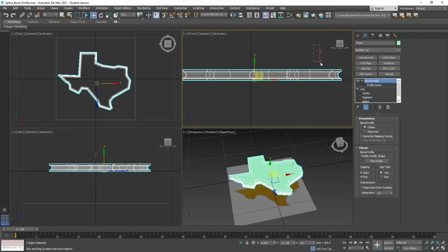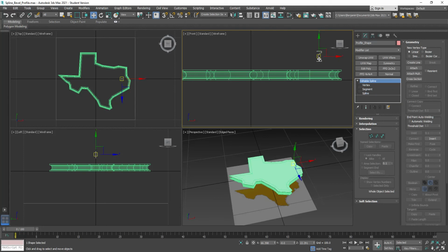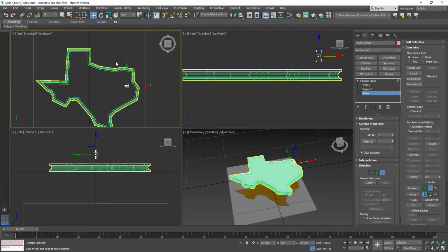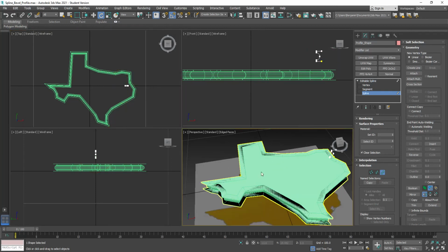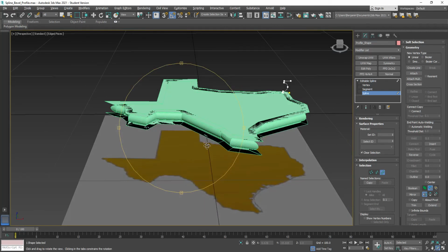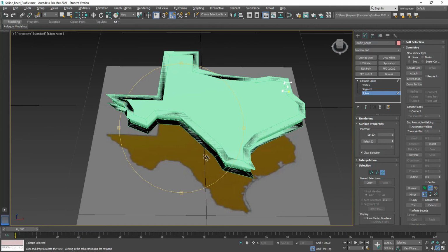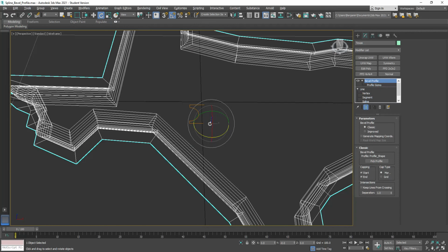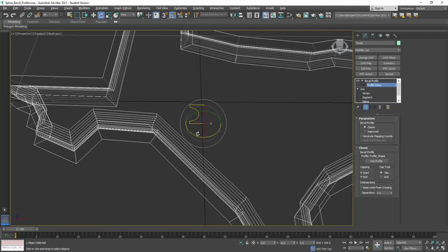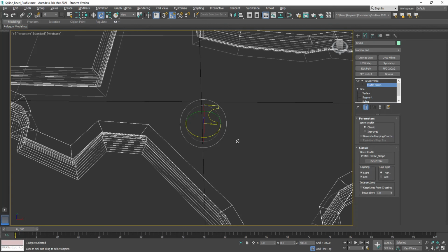Right? Because here's what happens: I have this shape out here, this profile shape, and there's any number of things that could happen. Like if I take this and turn on my angle snap and go into rotate. For example, if I had this thing rotated 180 degrees, if I had built my model so that all the detail was over here on the negative X side, my model would be inside out, as you can see here. Right? You see how the edges are totally flat? That's because based on where it's sitting on that bevel profile, see how now everything is on the inside? There's the spline.